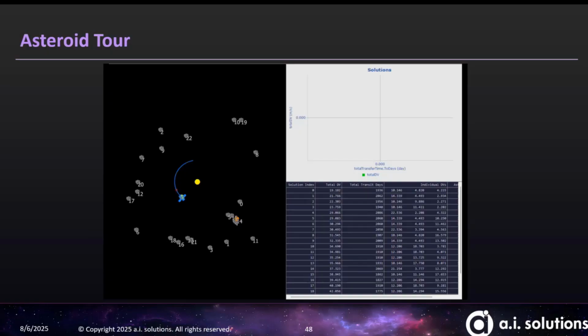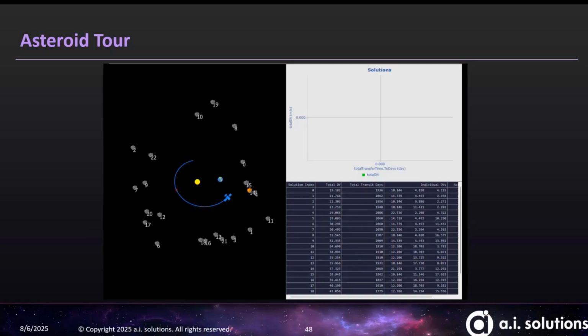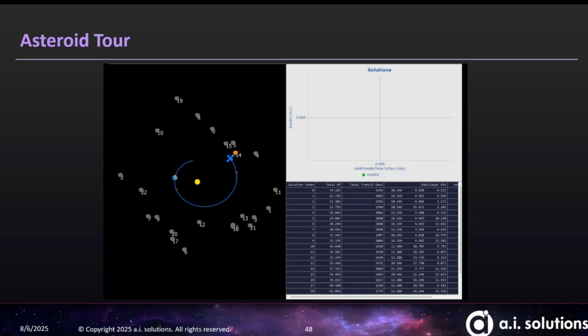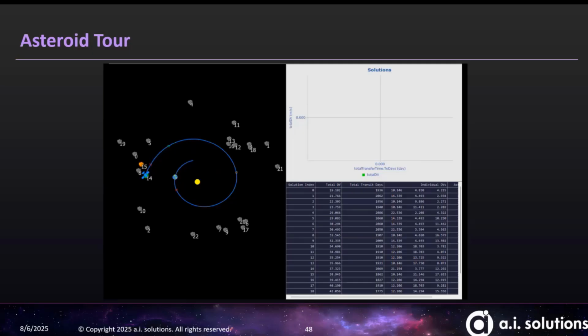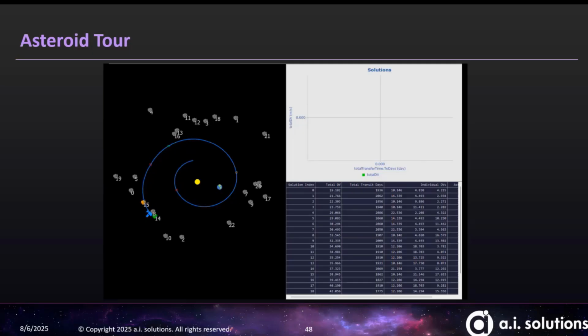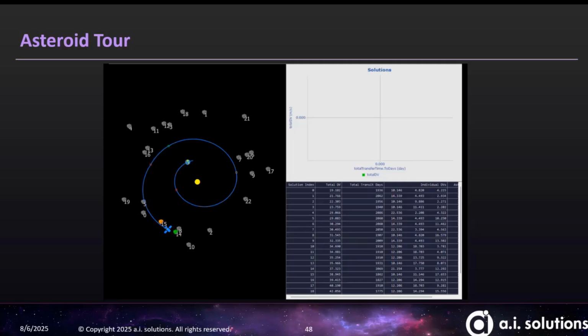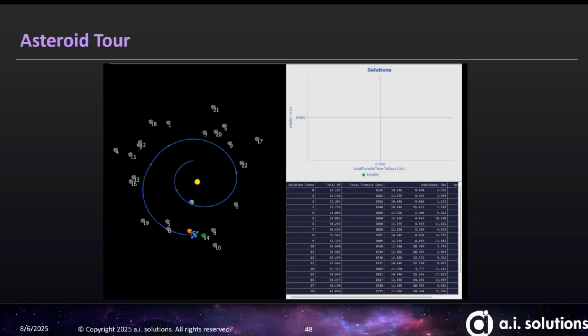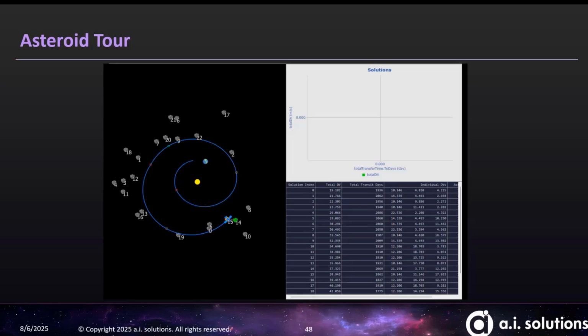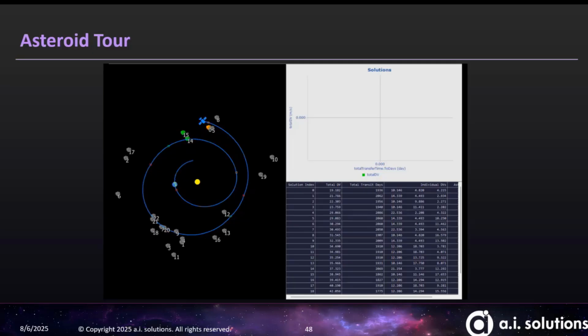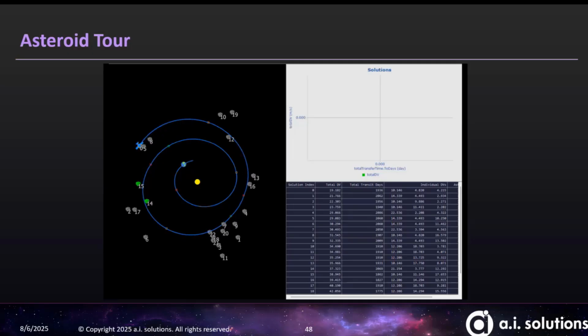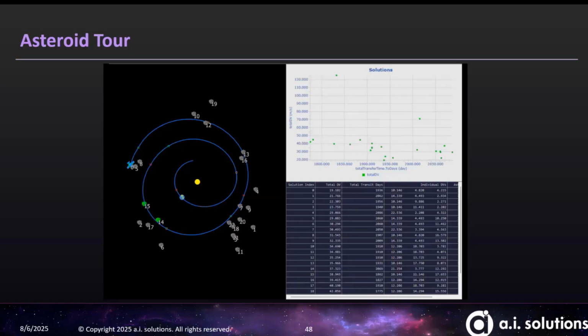Taking a step back to multi-objective optimization, this mission plan that Luke kindly helped us with utilizes the new multi-objective optimizer object to choose which asteroids a spacecraft should visit for an interplanetary mission while minimizing delta V and time of flight. The candidate asteroids are sorted by their inclination relative to the origin central body, such that solutions are only considered for asteroids within a specified relative inclination tolerance. Optimization is performed to solve for the transfers between the origin and destination, with the objectives to conserve the desired number of asteroids to visit, minimize the total delta V, minimize the total time of flight, and also minimize the delta V for each transfer.